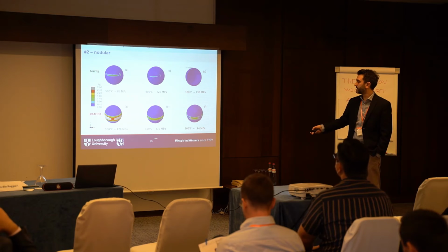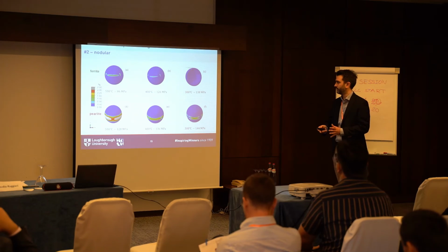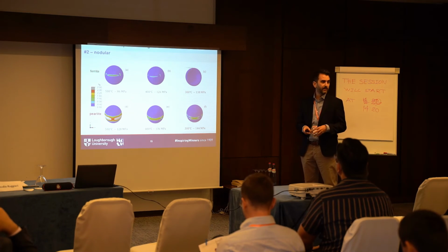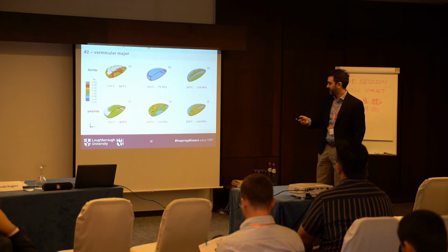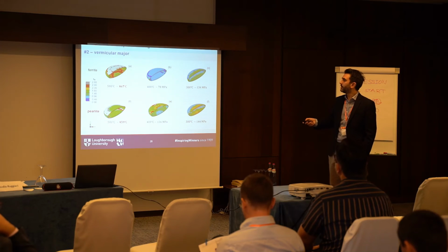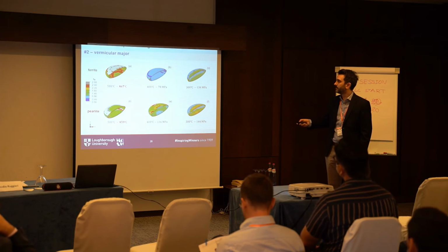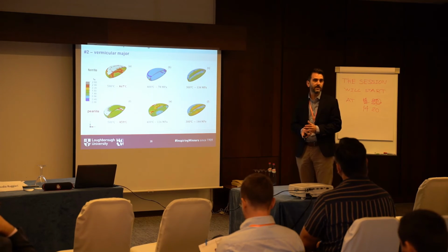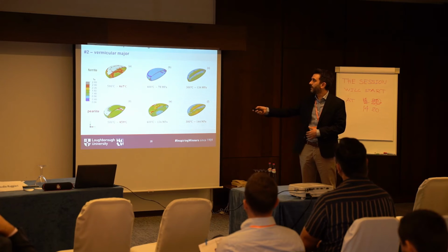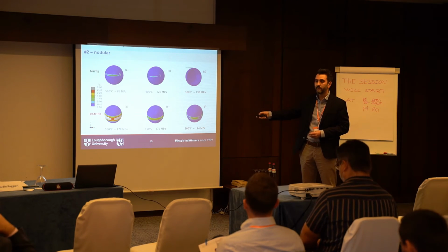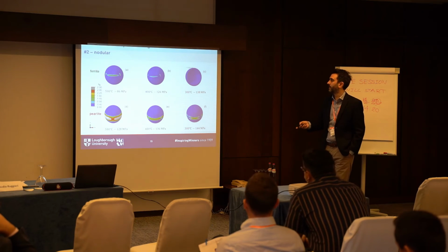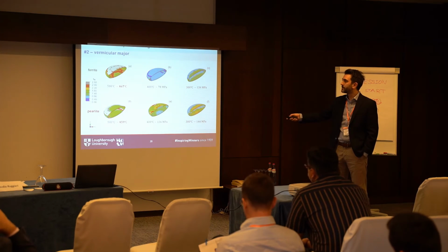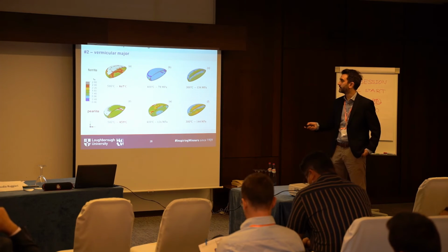So 126, 136, these are pretty close among themselves, okay, but still there is some shielding, there is some protection from the perlitic layer there. The same effect you can observe in the vermicular. What is to be noted here is that in this first case you get damage initiation just by thermal load, and this is consistent with our prior studies. So if you heat up something quite elongated and not with perfect axisymmetry like the spherical particle here, you have damage at around 400 something degrees.